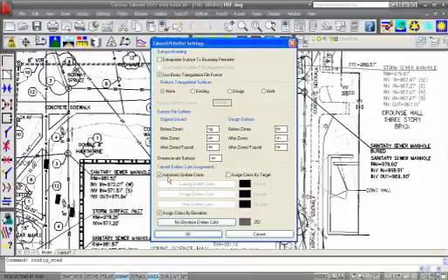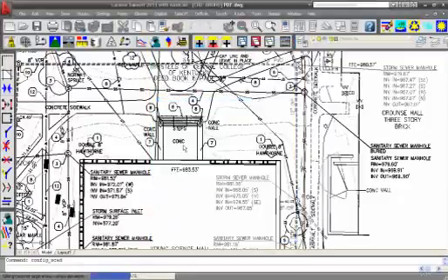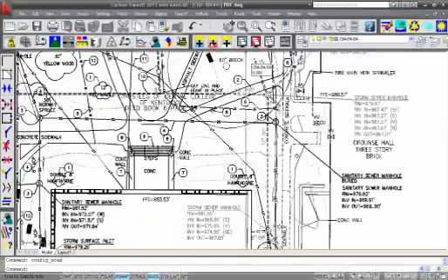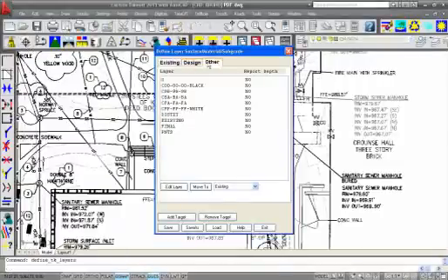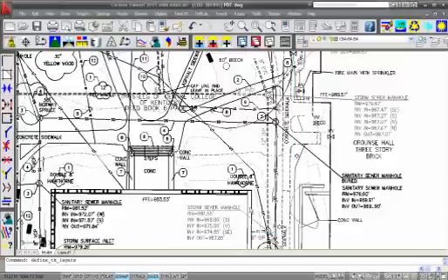We have an option here to automatically update the colors for the entities and assign them gray so that you can see what's elevated and what's not elevated. I'm going to check off that option because I'm working with gray line work here. So let me say okay to that. And now I'm just going to organize things into everything right now. All these layers that came in are under Other. I'm going to put some in Existing Design and leave some in Other. So set layer for existing.